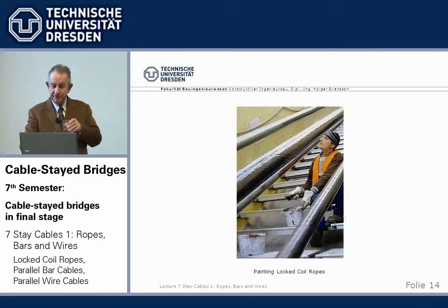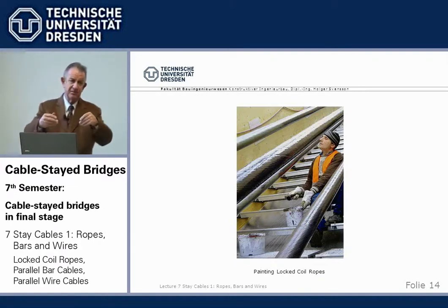So in total, we have today, and I always talk about the modern, there was a major development. We have the individual Z-shaped or round wires. They are galvanized, verzinkt. Then, when they are bundled, the little pieces called interstices between the wires are filled with a corrosion inhibitor.